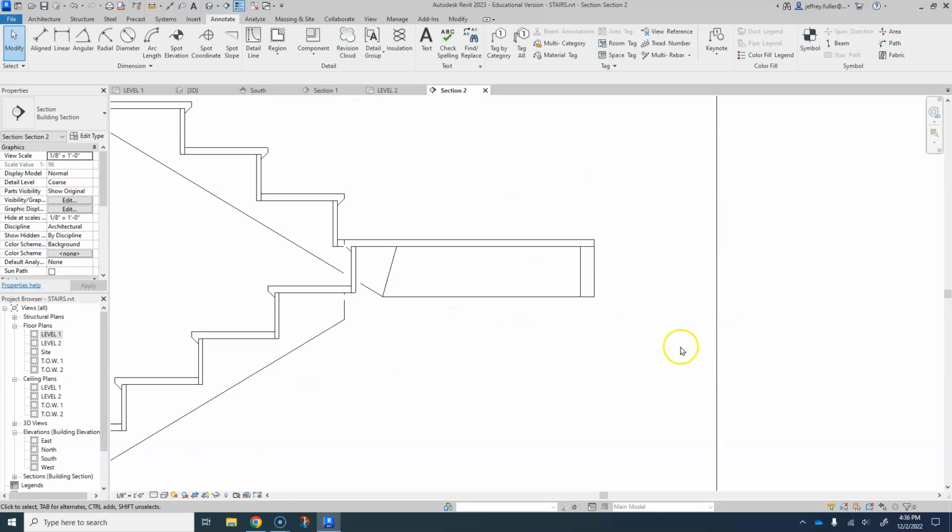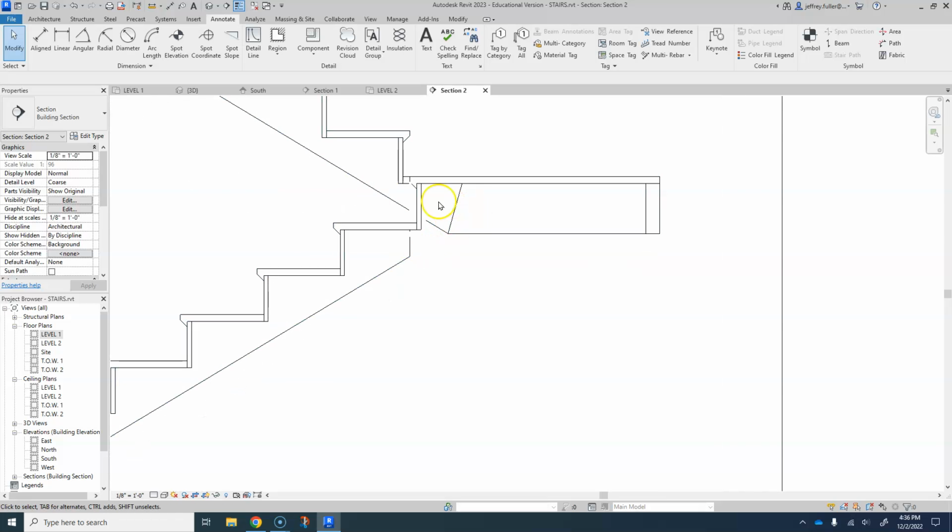Typically, you're going to have a wall already over here on this side. This would probably be hopefully an exterior wall, but definitely a load-bearing wall. And this would be attached to that wall. Here, I have to build a wall to hold it up on this side right here. So I got to think, how am I going to do that? Okay. First, I need to go ahead and build my floor system.